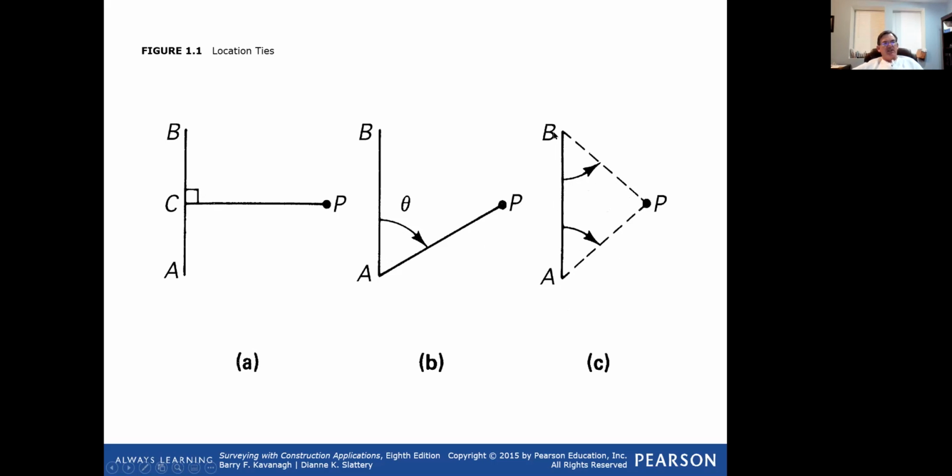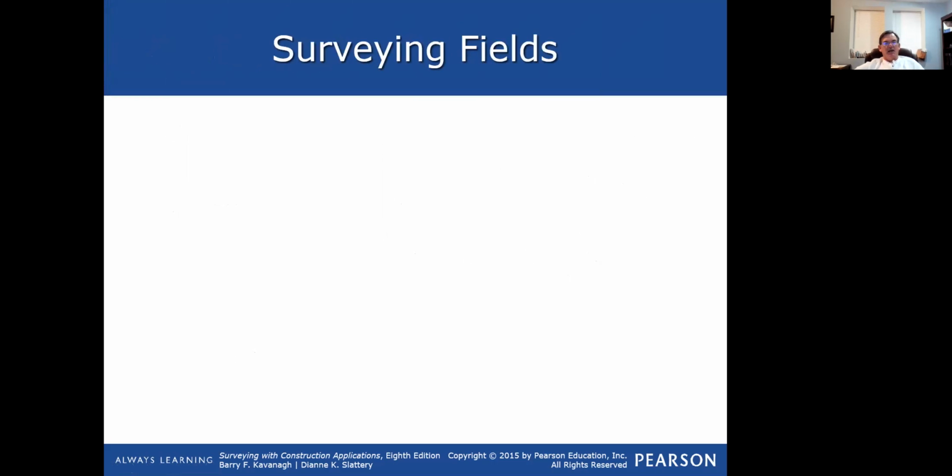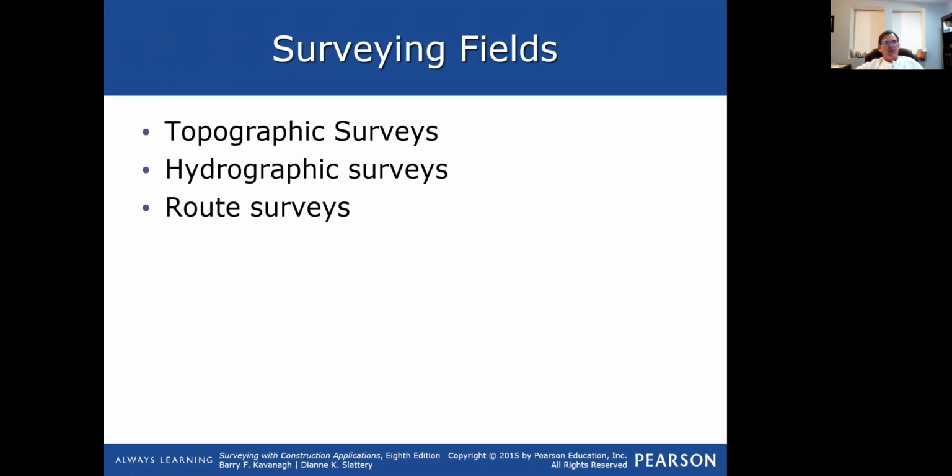You have known positions A and B, you turn an angle from each end and sight the same point from two different locations, and you can use trigonometry to figure out these distances and that location. I've done that many times. There are reasons for it, but again, the polar tie-in or polar locate layout, the way your book describes it, is the number one way that surveyors measure, and it's the number one way you're going to measure if you're out following behind surveyors.